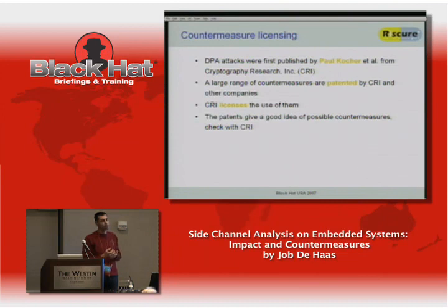The thing about it is also that I've shown you all kinds of simple ways like noise induction and things like that. But to do it really well requires a significant effort. Creating a masked implementation of an AES is not a trivial thing. And they actually also have quite a bit of knowledge in this area.